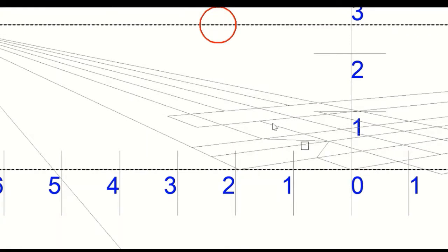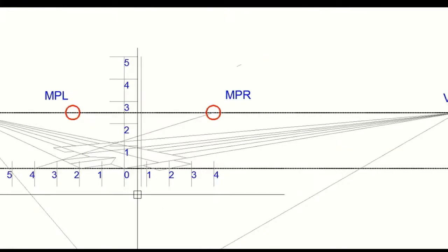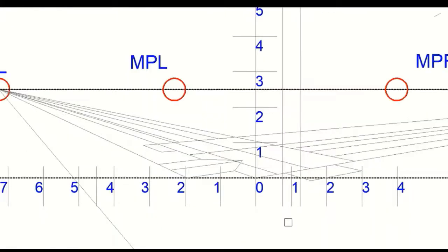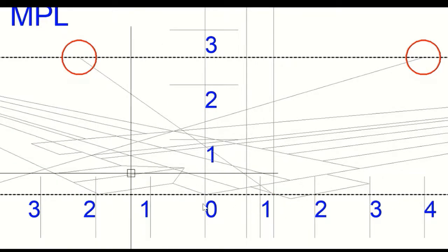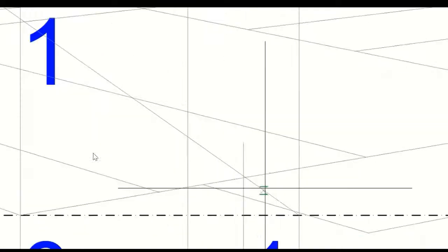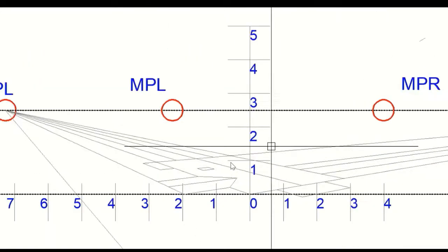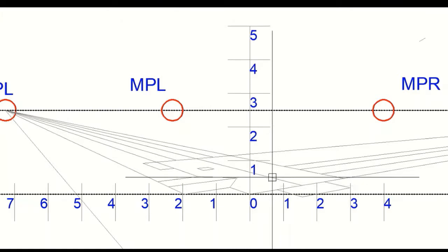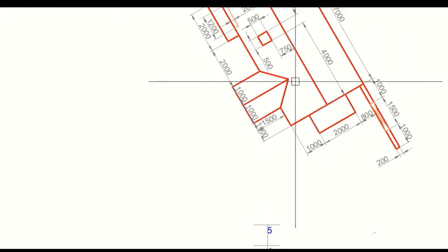You can see here, somewhere here it is taking the length from here, joining to the measuring point, and then for this, so this point has been created. Now this wall has to be created with the same method.